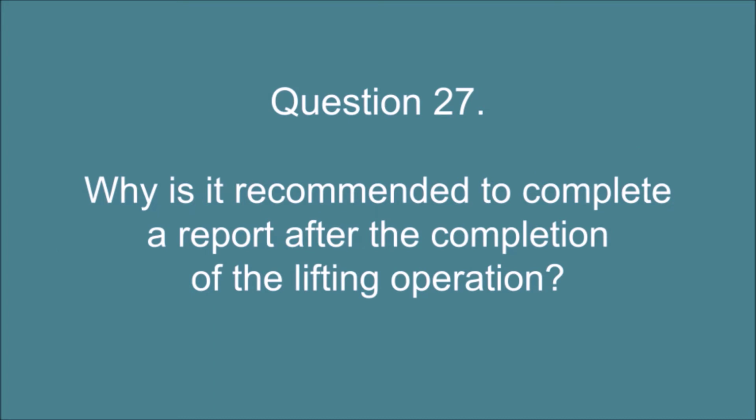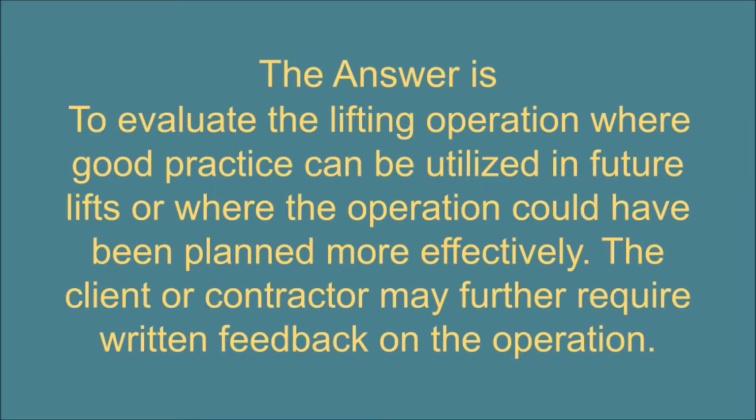Question 27. Why is it recommended to complete a report after the completion of the lifting operation? The answer is to evaluate the lifting operation where good practice can be utilized in future lifts or where the operation could have been planned more effectively. The client or contractor may further require written feedback on the operation.